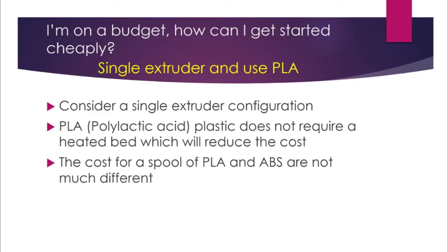Also, PLA plastic does not require a heated bed, so that's also going to cut down the cost quite a bit. You're still going to be able to create some outstanding prints, so it's not a huge deal. But if you're going to be printing a lot of stuff that requires a greater tolerance in temperatures, then you'll want to use ABS, and in that case, you'll need a heated bed.